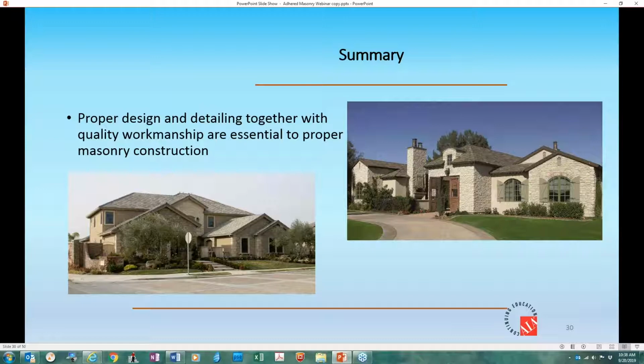Okay, this must be the follow-up maybe. What function does the drainage mat have on wall performance in a thin adhered veneer system? That one would be where if you have a drainage plane, it would allow for drying of both sides of your adhered veneer or your thin veneer. It will also enhance the ability for the drainage down to the weep screed, and then it'll also give a shorter period of time that a saturated scratch coat could offer direct contact of moisture to the substrate.